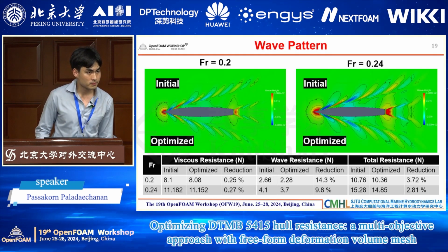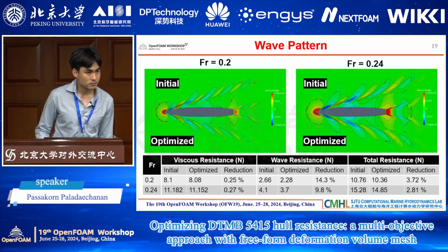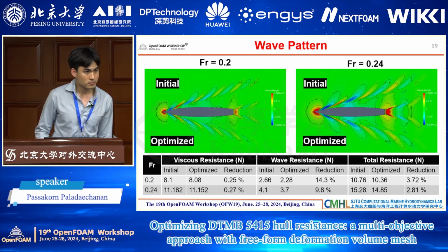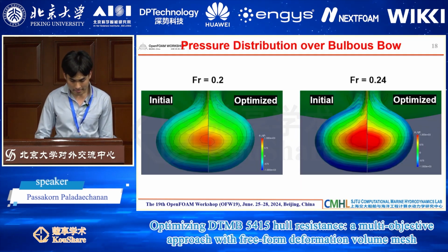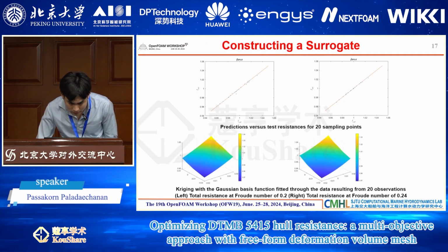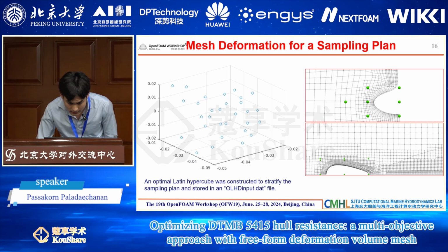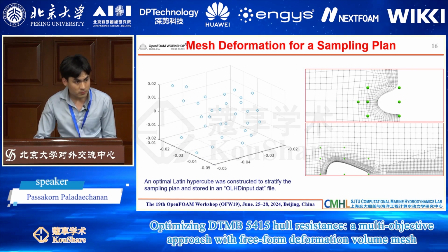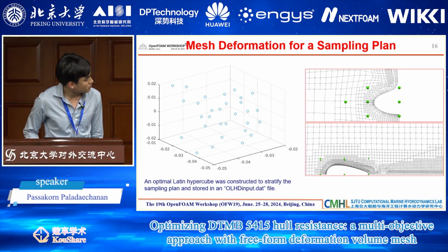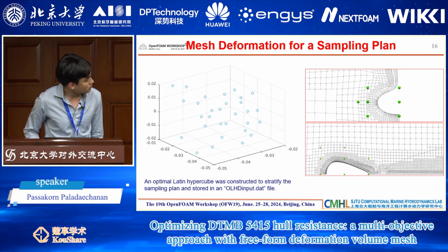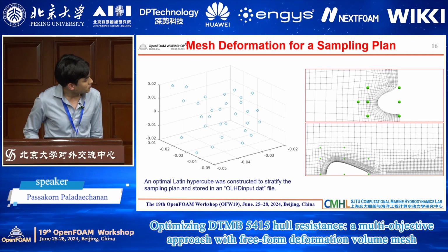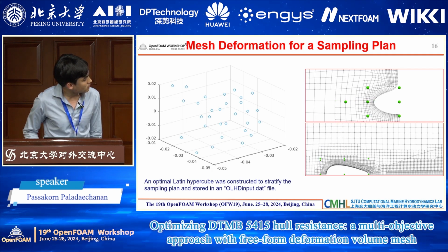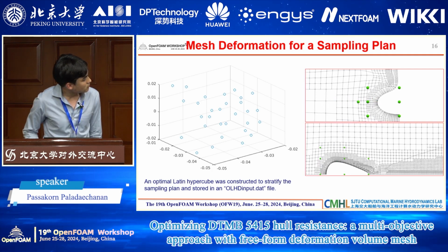Did you have any problems with free-form deformation parametrization or optimization? Okay, so on page 16, I think you show the motion of the points. You see what you have here is 7 points, and you only move the middle one, but you don't move the 3 on the left side. So when you run optimization here, you only have 1 degree of freedom, right?